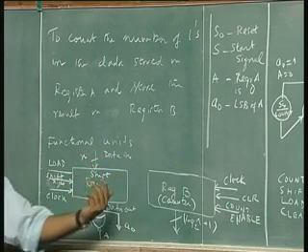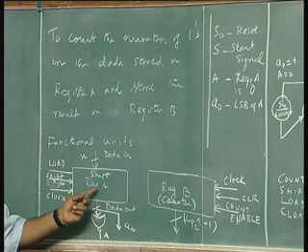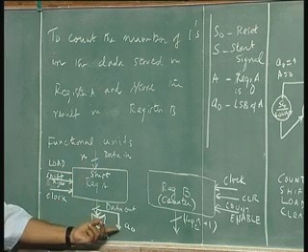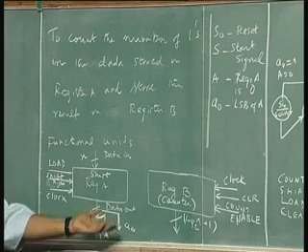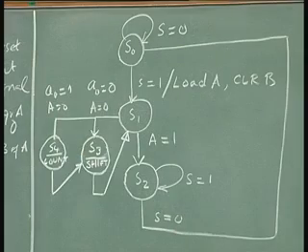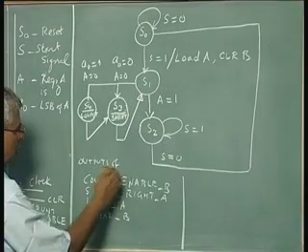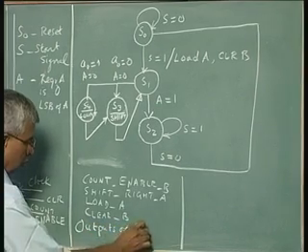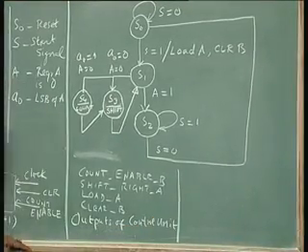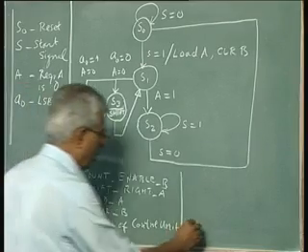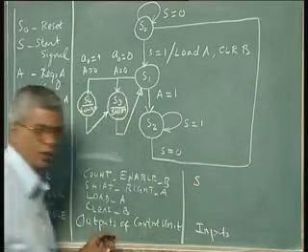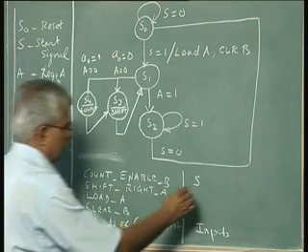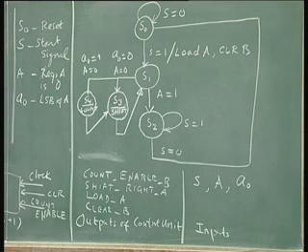So, the two extra inputs which we did not think of in this case are the LSB of the word and the 0 value. 0 value is called A is equal to 1 means register A's value is 0, A0 is the LSB, that is because all the bits are available, the least significant bit you take and put it. So, these are the outputs of the what? Of the control units. Inputs of the control unit are what? Yes, start switch, is not it? It is an input to the control unit. A, value of A and A0. Anything else? No.